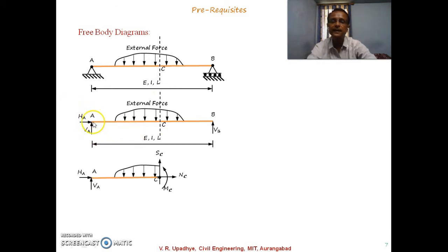Okay, so at A we have hinge support, so two reaction components are there, vertical as well as horizontal. Some part of the loads acting in between that position, and the internal forces. The internal force may be axial force and another vertical, which is shear force, and there will be some moment getting developed due to these active and reactive forces. So that is moment, or generally we discuss now as bending moment.